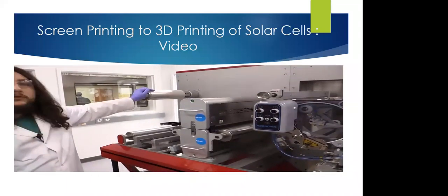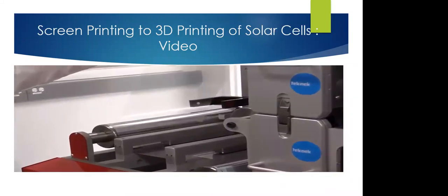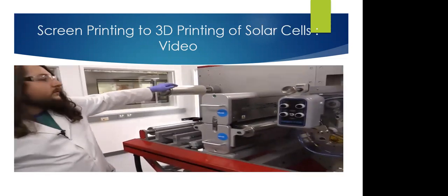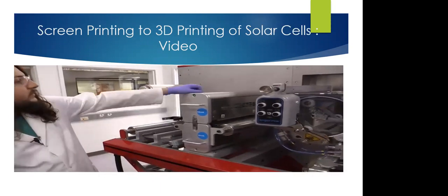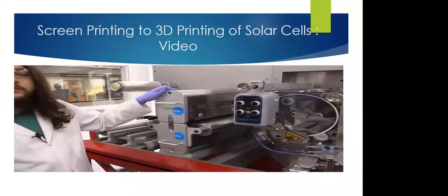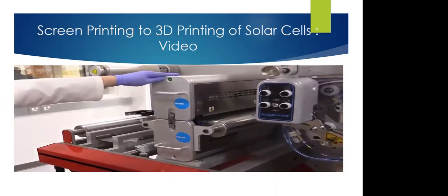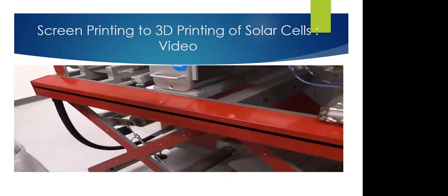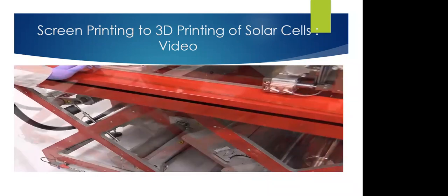This can be treated with either a transparent conductive oxide or be run as just plain substrate, depending on your application. The first step that we have to go through is rolling it and cleaning it to prepare the substrate for printing. So the first step is a static cleaner. We are discharging any static electricity and then using a rubber roller to pull off any particulates. The roll then travels down to the corona plasma treatment to both clean the substrate and modify the surface energy to assist in printing.